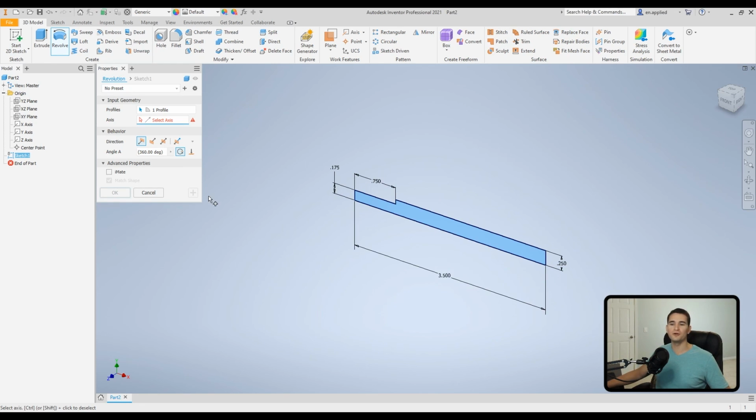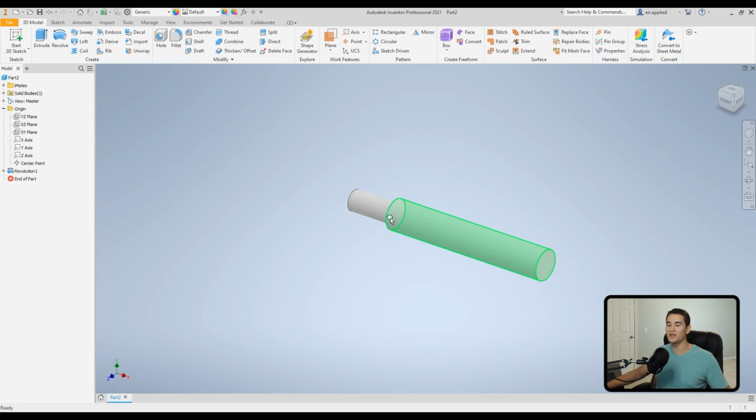So say, for example, we're creating an assembly where the shaft will fit, have a concentric mate with a bearing. And we want to automate that process because for whatever reason, we're using these parts and mates, or constraints, several times over again, and we don't have to manually do those individually. Well, we can automate that process when we create our revolve features. So if I check that and just select my axis and hit OK, you'll notice we get our iMate option there. So we could come back and put a bearing over this part and just sort of automate that assembly process.